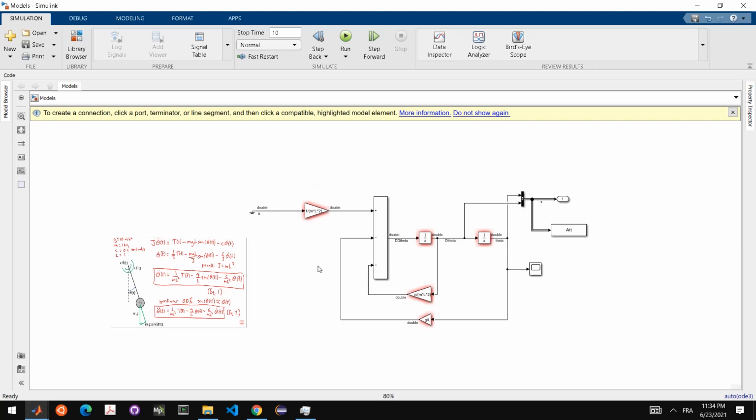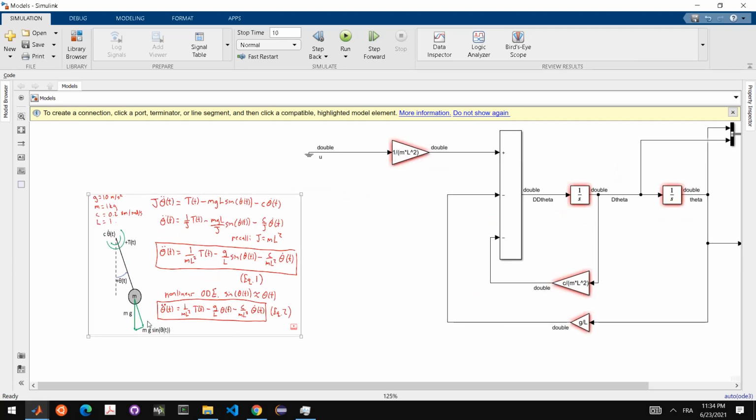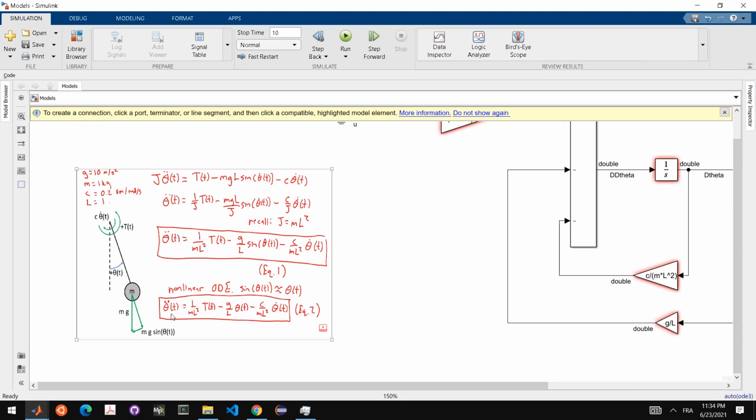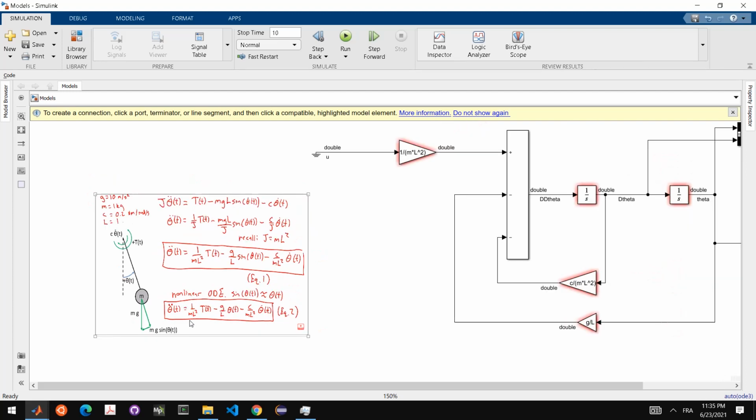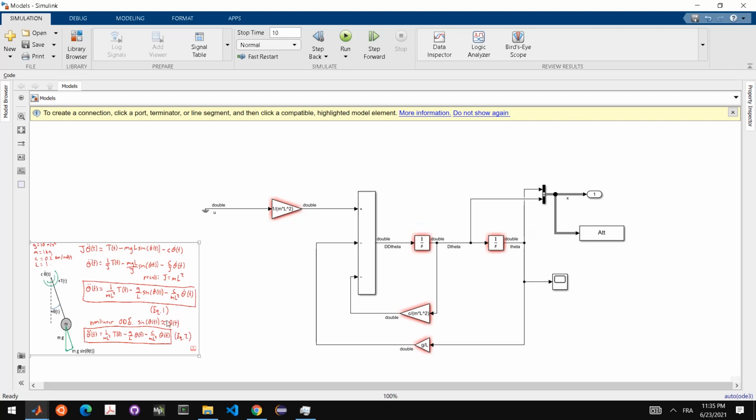In this example, this is the dynamics representing a normal motorized pendulum, and this is the full differential equation giving our dynamics. The same dynamics, the pendulum, could be represented through this model. We'll take the output, which are theta and the angular velocity, and send them to the workspace to use afterwards if we need to plot this data or analyze our simulations.